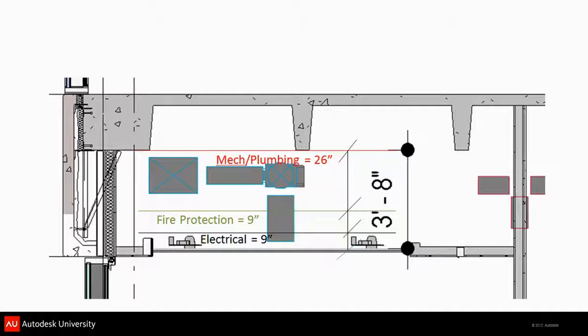Even if fire protection is not on board yet, we assume where they are going to go. And then when they do get on board, we ask where their mains are going to run. We just use a product where we can take a screen capture and draw up these zones. Then we talk about where the large pipes, like roof drains, are going to need to pass through, where they're going to start high and where they need to slope from. And this sketch, before we dive into the models, saves hours and hours of time.